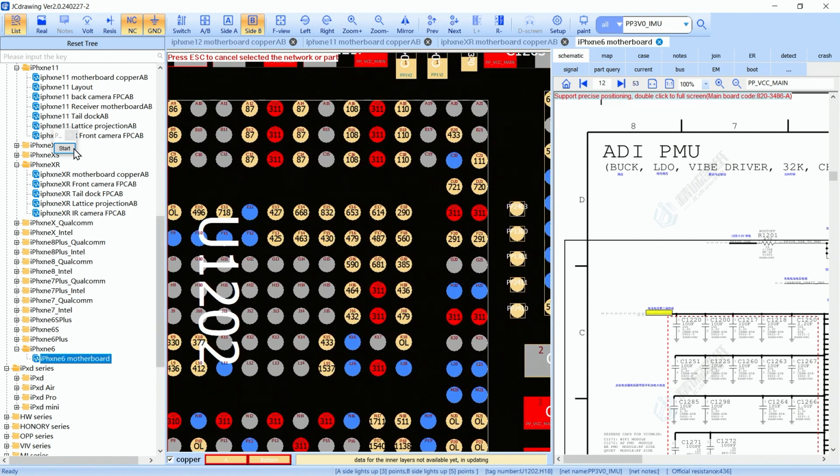So for example, what happens if you remove one component and you lose these pads? You are missing two pads, the E20 and E21, but you can't say, okay, I'm not going to put these pads back because I have these ones close together and it's the same thing.